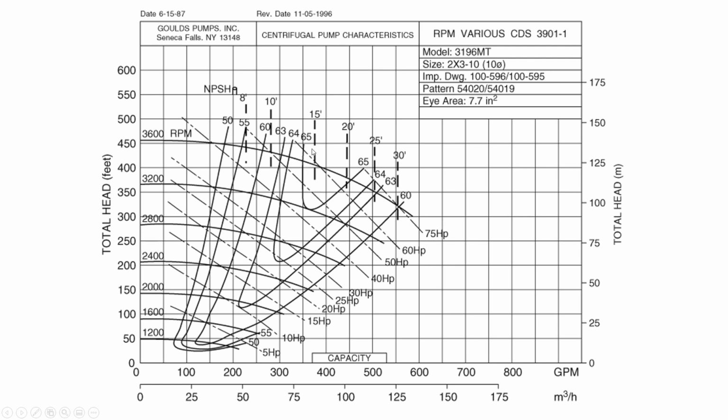And of course, it can add head and it can move water at other rates besides that optimal range. But just from the perspective of energy consumption, it's going to be most efficient when you're operating it here in this zone than outside that envelope.